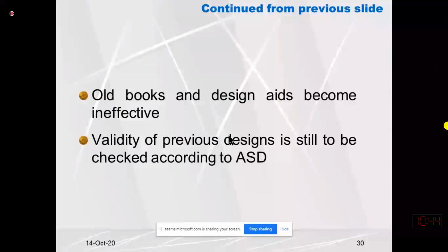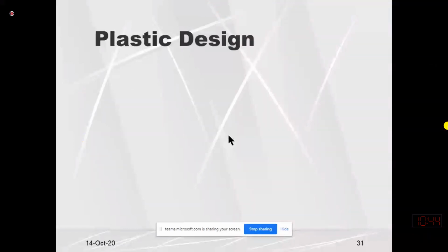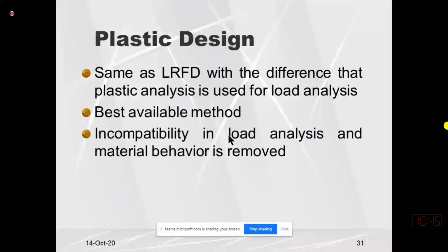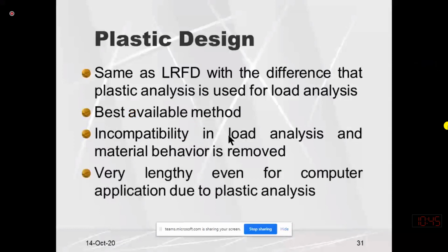So plastic design, I'm not going to explain, but I will just give you one clarification. You can read it and understand yourself. Plastic design is similar to LRFD design. We can increase the load by a certain factor of safety, but the material strength we are not using less than or equal to Fy. So phi Fy will be equal to either the yield value or more than the yield value. So that method will be called plastic design.